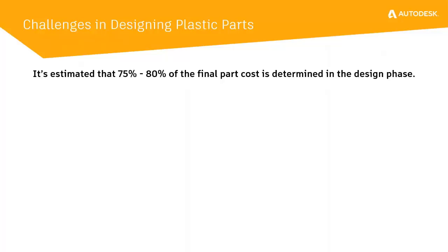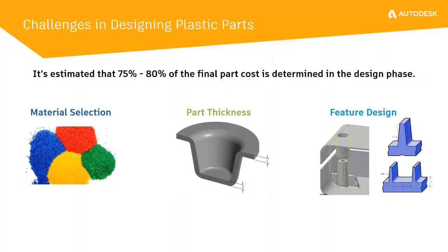For example, can the part be filled with a selected material? What about alternate materials? What happens if I make the part thinner? Can I still fill the part with the pressure limitations? And will the part still meet structural requirements? Based on my experience, I feel that simulation is not run early enough during the product design stage to answer these questions. But when simulation is run at this stage of the development process, changes to the part design can easily be made and can be made before things get expensive.